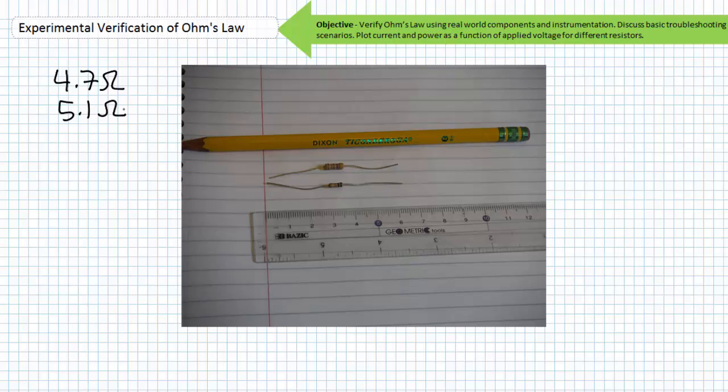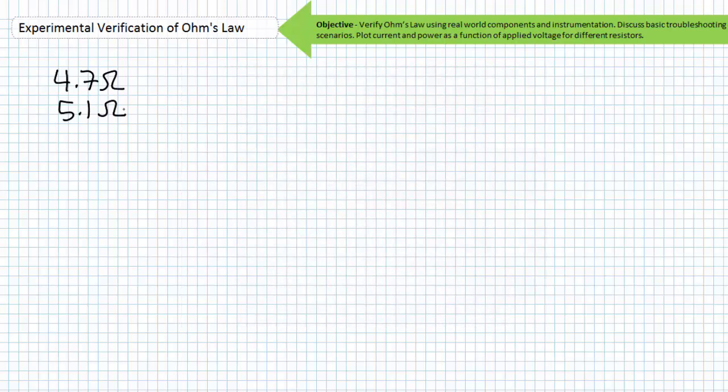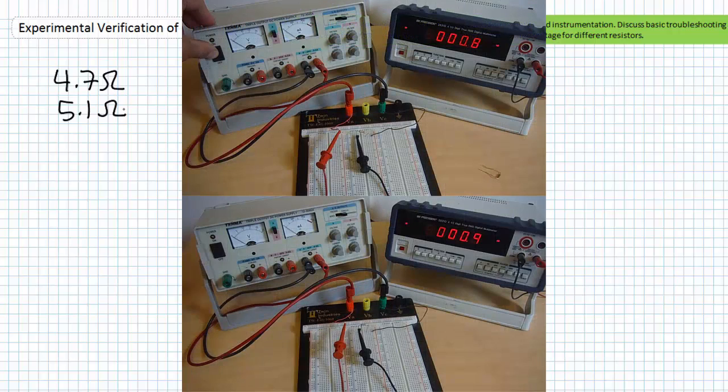Let's have a race. Who's going to go up and smoke first? Quick hint. What does physical size indicate about a resistor? We're going to use a power supply that maxes out at roughly 571 milliamperes of current. Ready, set, go. Both of them are drawing the maximum current. All right, smoke curling off the 5.1, 4 seconds into the game. 4.7 still holding. Smoke alarm is going off.